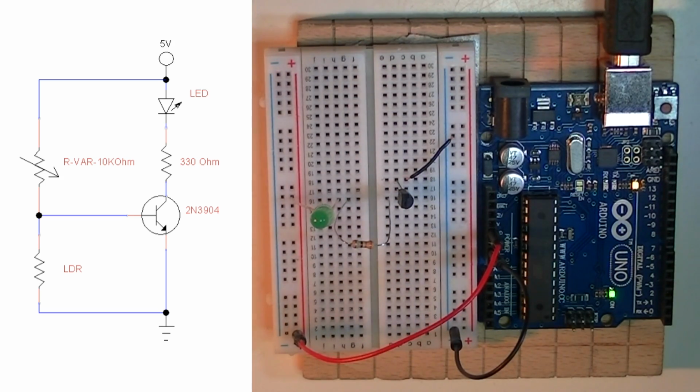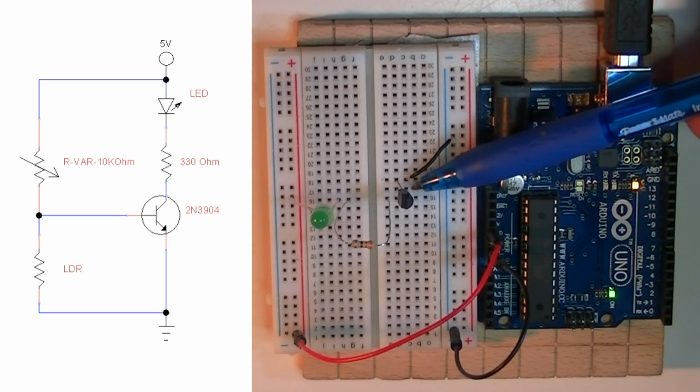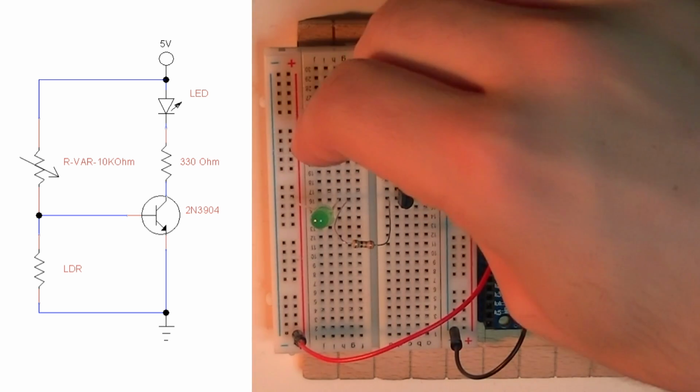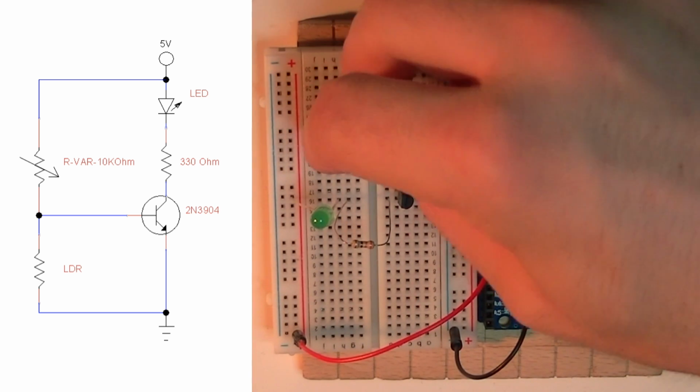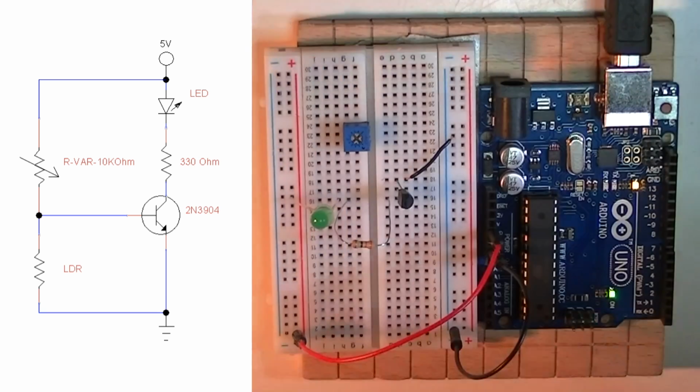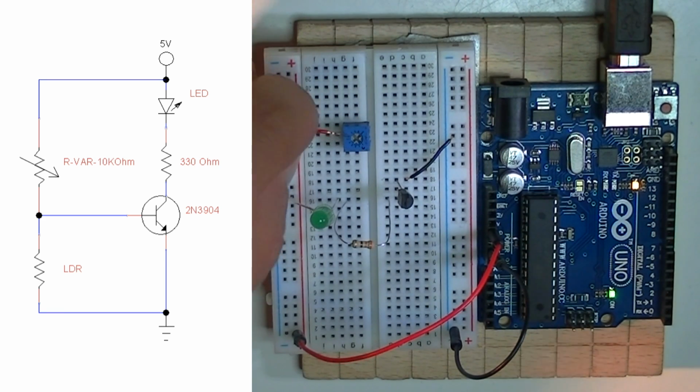So right now the circuit should turn on when the current through the base gets high. And what makes this interesting is, well, we're going to turn this current high when the light is low. So the way we're going to do that is we're going to connect, firstly, a variable resistor into our base from the power line. So if that's power, it's going to go into here.